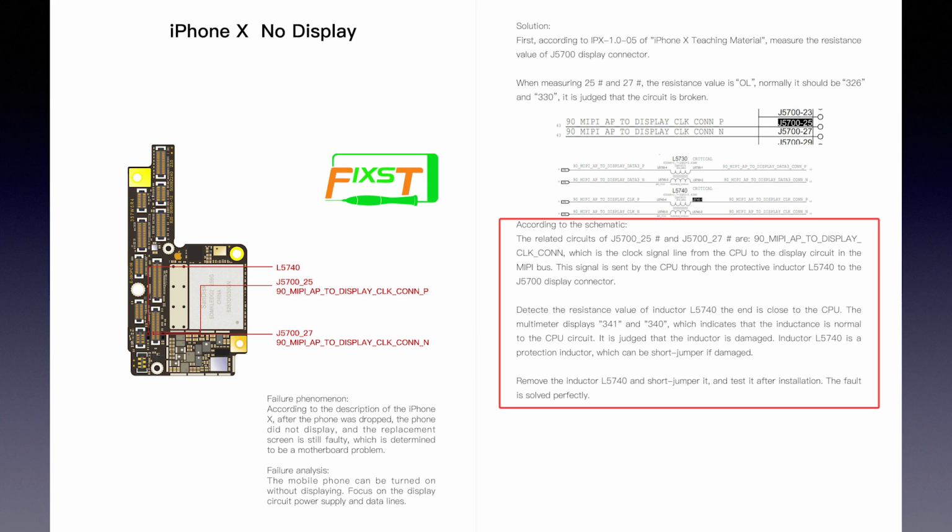Inductor L5740 is the protection inductor, which can be short jumpered if damaged. Remove the inductor L5740 and short jumper it and test it after installation. The fault is solved perfectly.